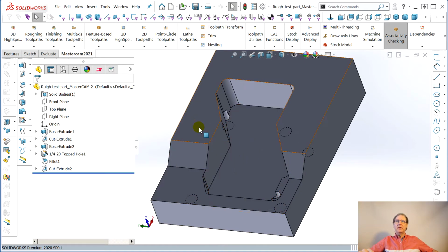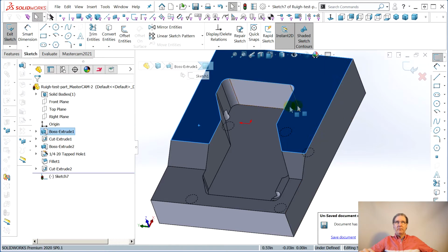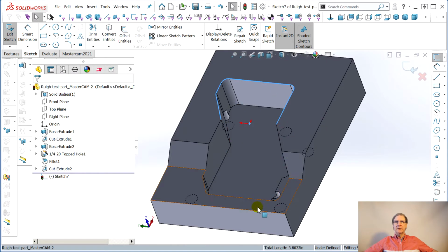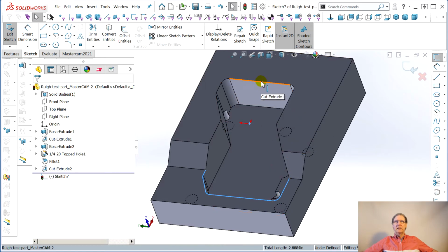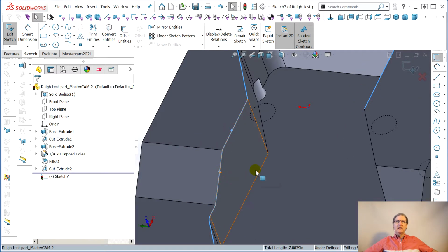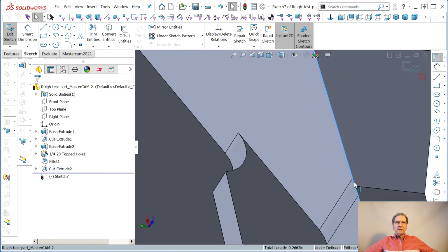What are we trying to do? We're trying to do a plane up here. We'll say plane. That'll make a plane in the same plane as the top face. Then we want to do our tangency business. Select tangency. Select, didn't hold the control key down. There's a thing called design momentum. And when you lose it, it takes you 10 times longer to get something done. Hold the control key down, Paul, or you'll start doing it all over. And then the little one everybody forgets.